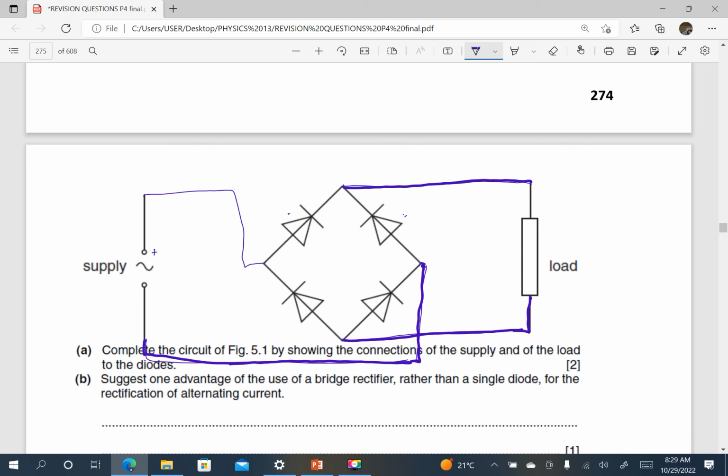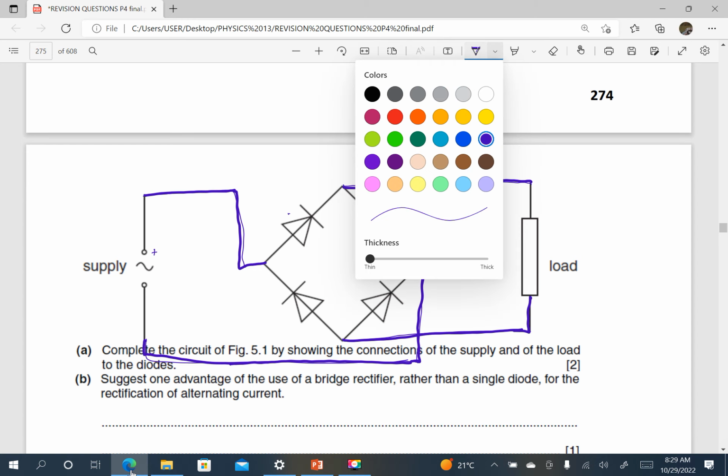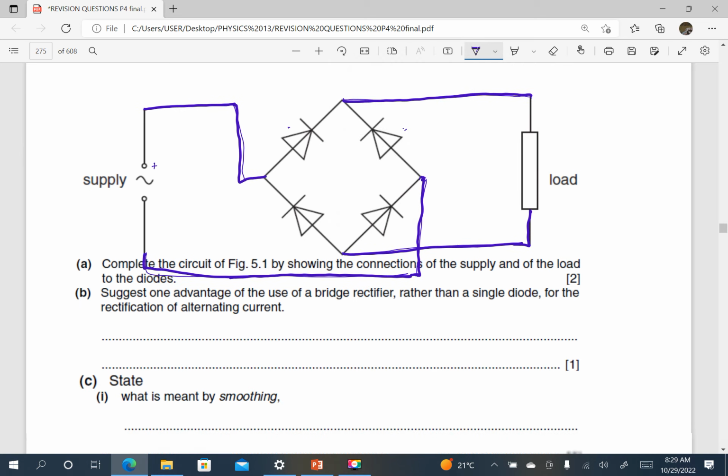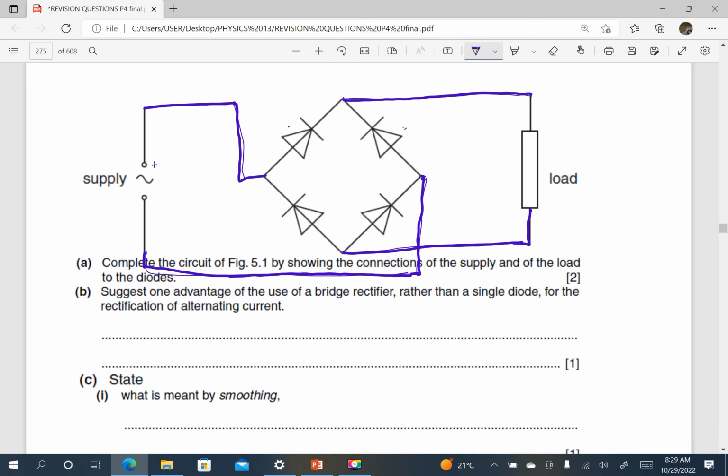You first draw with a pen, so as you move around you navigate around your connection to see if there is a complete path to the load. And you reverse the terminals to see if the current is entering the load from the same side. If not, then the connection is wrong, because this is full wave rectification.